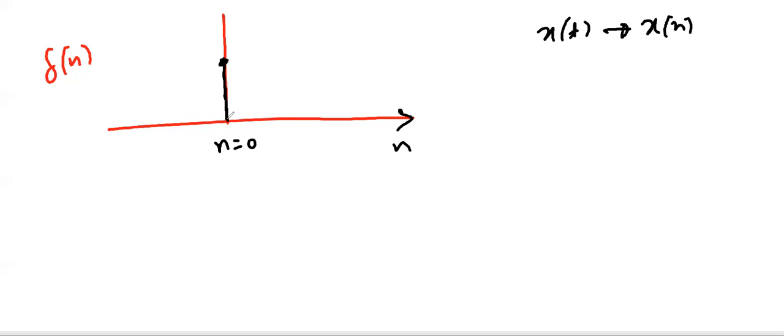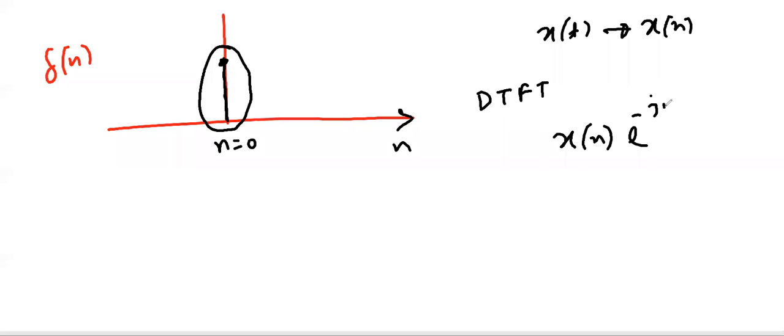If we do the Fourier transform of this stem, then we can find what frequency components you need to build this stem. So what do we need to do for the discrete-time Fourier transform, what is the definition? That is x[n] e to the power minus j omega n, where omega is the relative frequency. Make a summation from minus infinity to plus infinity, and no d omega or dn, because this is a summation.